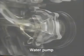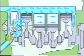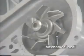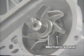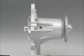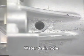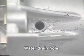The water pump forces coolant through the cooling system. The rotary motion of the crankshaft is transmitted through the timing belt and V-belt to drive the pump rotor. The pumping function of the rotor circulates coolant in the cooling system. The gap between the rotor and water pump body is mechanically sealed to prevent coolant leakage. If coolant leaks through the mechanical seal, it can enter the bearing section. To prevent this, the water pump is provided with water drain holes. Coolant leakage can be checked through these holes.